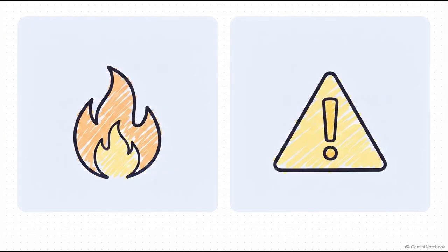Okay, this next part is a massive exam alert because these numbers get mixed up all the time. For hot weather, your shotcrete material temperature limit is 95 degrees Fahrenheit. But your reinforcement and receiving surface limit is slightly lower, coming in at 90 degrees Fahrenheit. The absolute most important thing here is not to confuse these material and surface limits with the ambient air temperature. They are completely different measurements, so don't let them trick you.